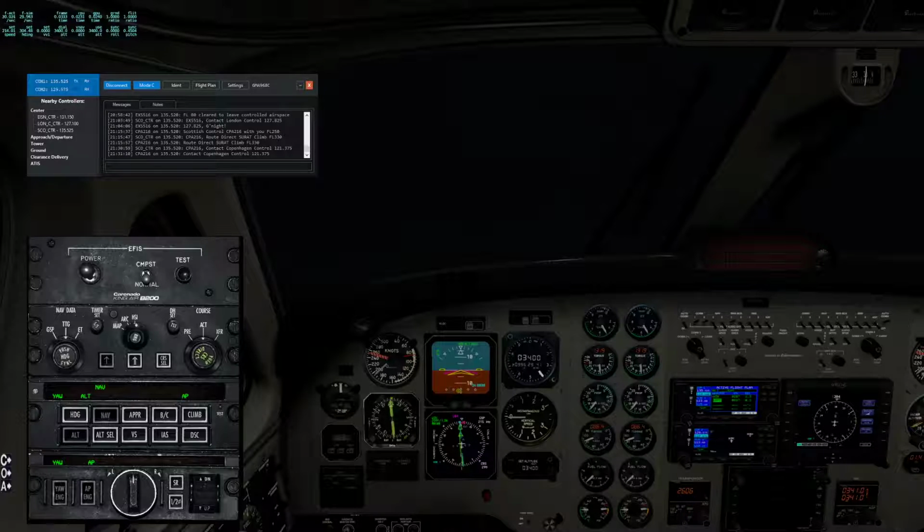So we're now approaching the VOR at 1.3 miles. Once we cross over the VOR, we need to track outbound. And looking at the chart, the radial is 292 degrees for Cat C and Cat D. I don't know if we're Cat C, we're probably a B plus or something, so probably I should have gone for something in between the 292 and the 303. Those are the two options. But I go for 292.